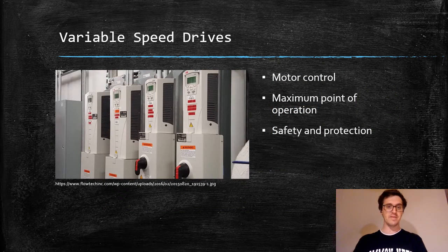Variable speed drives have several functional advantages. The load can be shared by each of the rollers, ensuring they wear at equal rates. If there is a change in ore characteristics, they have immediate roller response. Not only does this extend roller life, it also boosts yields by keeping the system at the optimum point of operation.